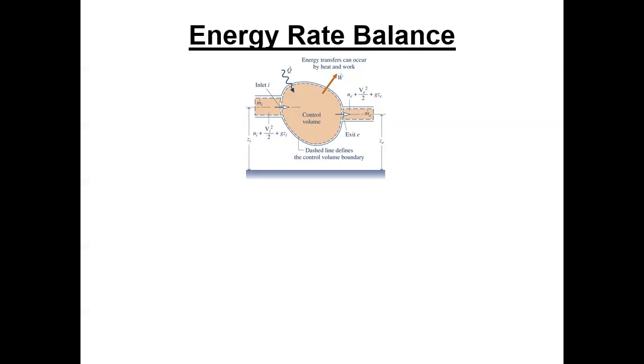We could be having, say, 10,000 BTUs an hour gained through the windows, but the air conditioner is a 1-ton air conditioner, which is 12,000 BTUs an hour being extracted. And so the net then would be 2,000 BTUs extracted from the space, which would be a negative for us because we got more going out than we got coming in. You can turn that around whichever way you want to make up the example. Okay, and then you've got the work term, and that's the net.